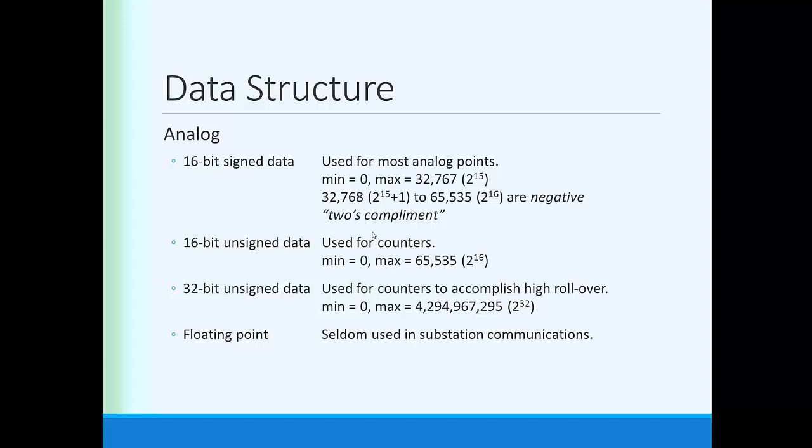As a result, when you define 100% of full scale in an analog way, for example, 5 amps on the low side of a CT. Let's say the CT has a rating factor of 2. That means it'll read up to 10 amps with accuracy. We would say 10 amps is the full scale. And 10 amps on the secondary side of the CT represents 32,767 counts as an integer. Anything below 10, say 50% of 10 is 5 amps, would be 50% of 32,767. And that's the way the integer for 5 amps would be represented.